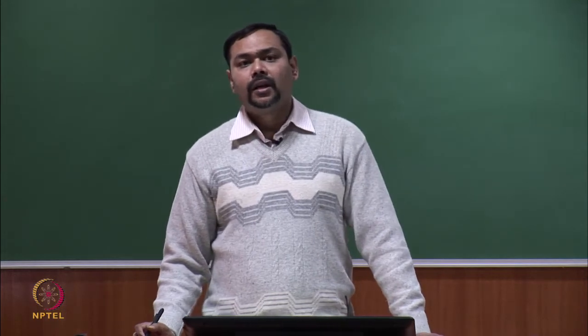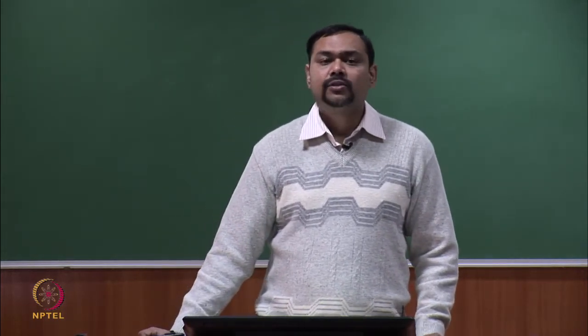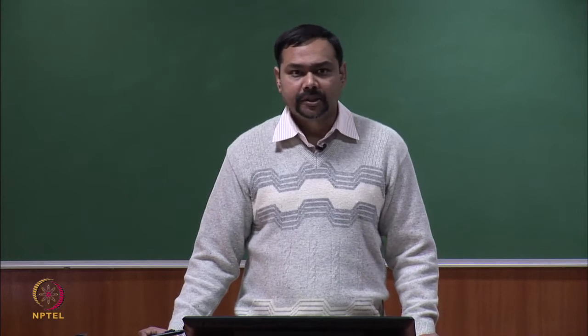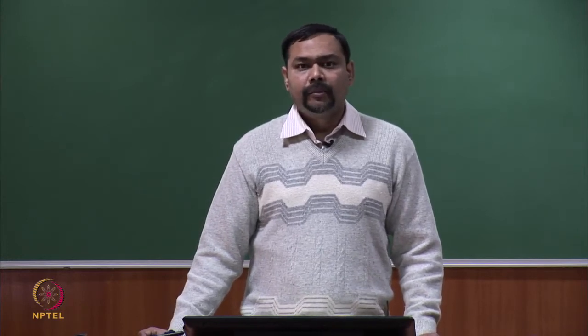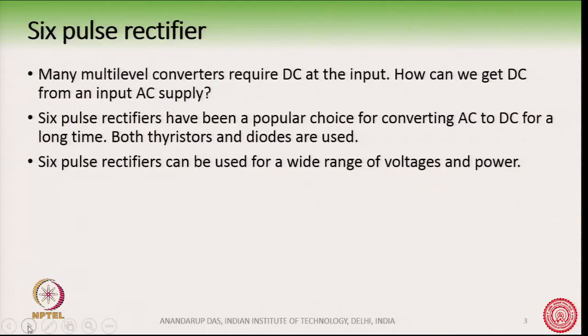So, why do we need to study multipulse transformers? Many multi-level converters, and not only multi-level converters but many conventional 2-level VSI or VSC, have a DC bus at the input. Now, the question is how do we get that DC?